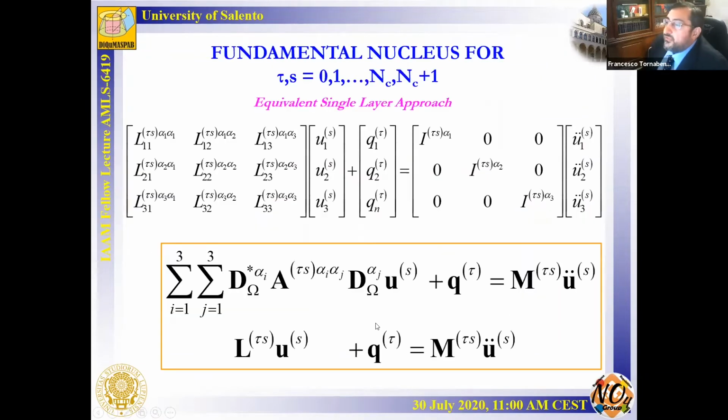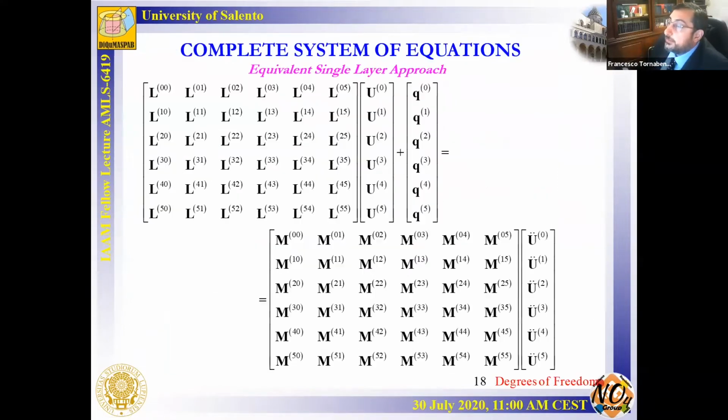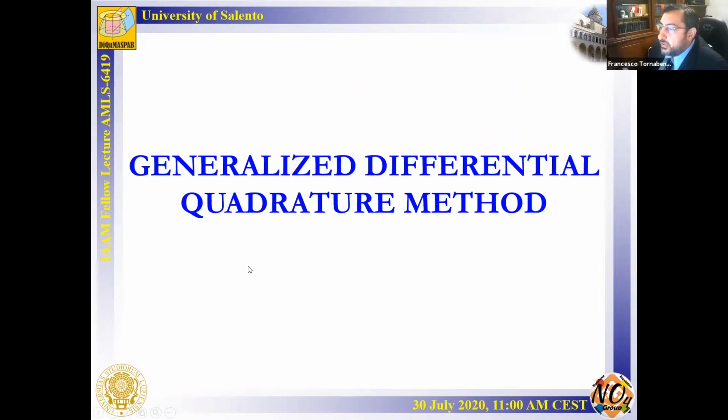After that, we can write the fundamental nucleus in terms of displacement defined along the reference surfaces, and then we can assemble the complete system of equations. But now we have to introduce a numerical technique to solve this differential system of equations. And in particular, I have used the generalized differential quadrature method.